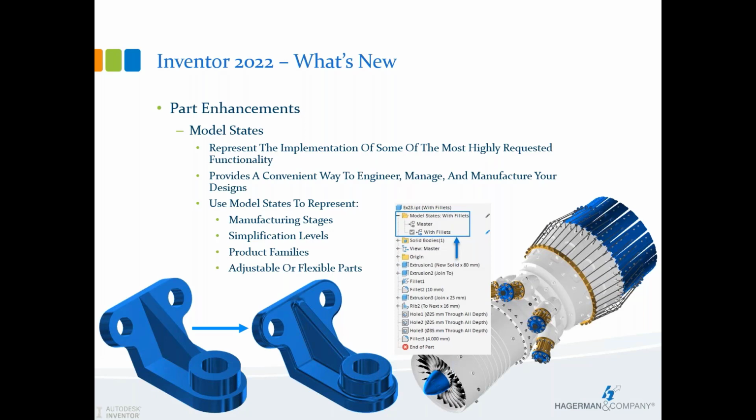So if it's a part and we're creating 5 different instances of this component, if it's an assembly and we've got 8 different instances of this component, we can control the instance properties via the iProperties editing dialog box. So if we've got example 23-1, example 23-2, example 23-3, I can go into each one of those instances and edit those instances of those components. And so it's replacing the level of detail from the olden days in the assemblies, but it's a great way to have multiple representations inside one file without having to use iParts and iAssemblies for those table-driven files.